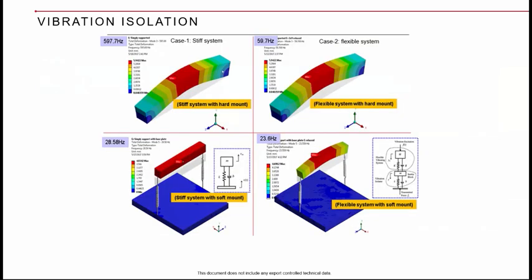So this is a simple beam. Okay. When you see it is stiffly mounted at the ends, the frequency is 597.7 hertz. And you can see a deflection mode shape. So that is not anticipated. I don't want such kind of behavior on this system. I assume that it is an electronic controller system. So now what I did, I have mounted springs on the ends, soft mounted.